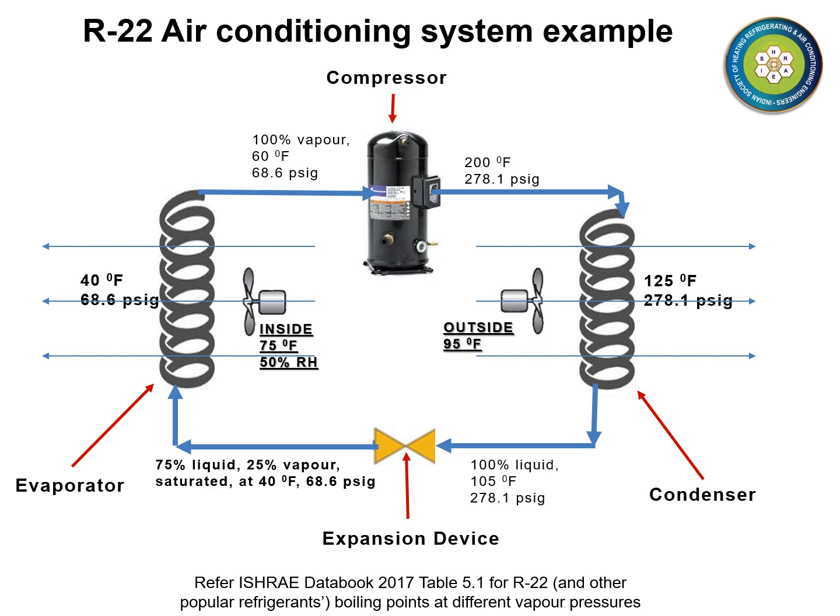The vapor now enters the condenser and begins its flow through it. And as it flows, it rejects heat to the outside air, which is at a lower temperature of 95 degrees Fahrenheit. Somewhere midway in the condenser, the vapor's temperature is down to 125 degrees Fahrenheit, whereupon it begins condensing into liquid.